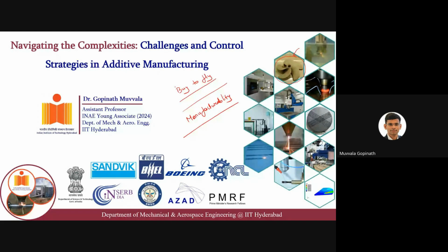Typically, if you are machining these kinds of components, impellers, then essentially you will be taking an ingot. From the ingot, you will be removing the material. And once the material is removed, you will get more or less this kind of form. And if you look at the surfaces, all the surfaces are curved. So essentially it requires a 5-axis CNC, and your tool should be able to access these zones, which are difficult to reach.